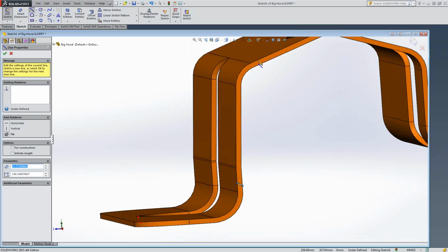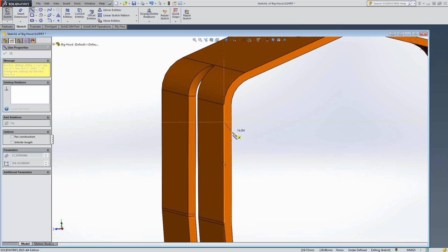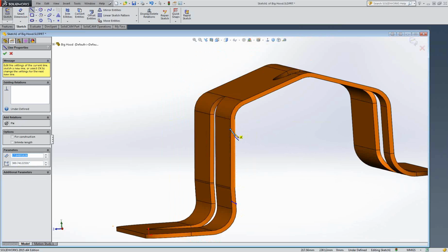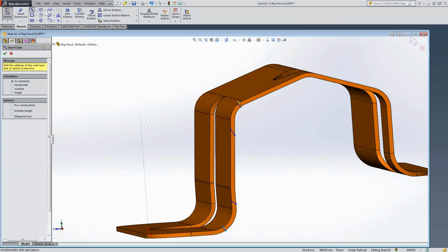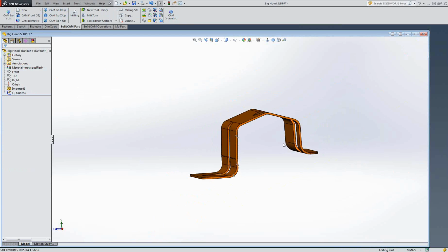As we come over the top here, we may want it to delay a bit as it comes round. We may want it to go down here like this, and then it will morph between that and that as we go round the corner. We can steepen it by the time that we're here. These are little tricks that allow us to control the way that the head moves on this type of machine.